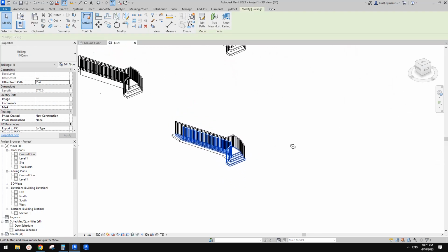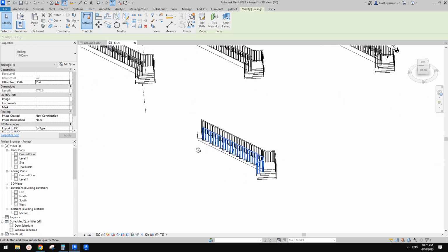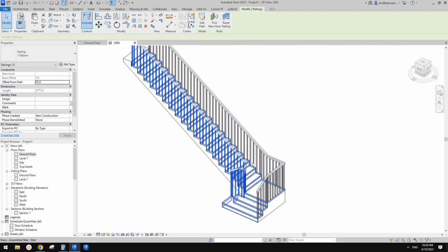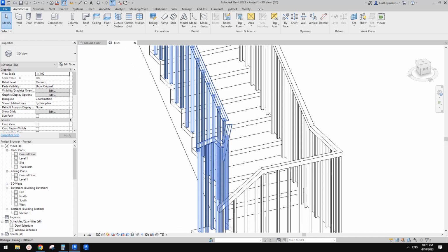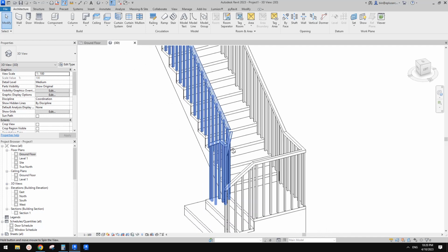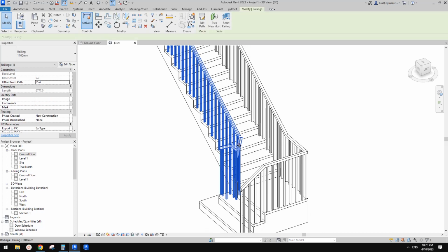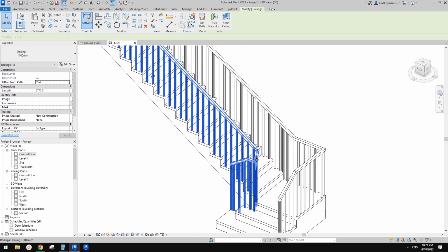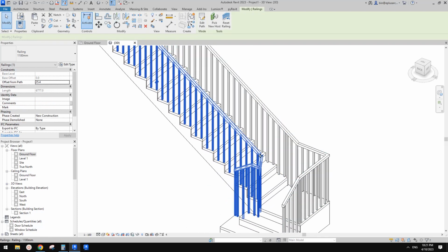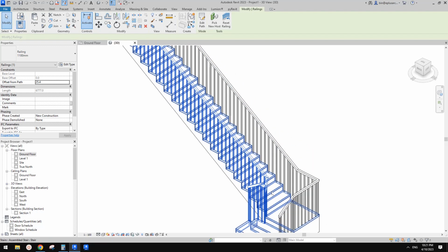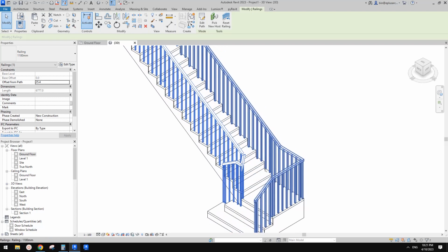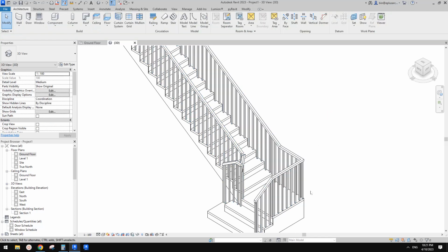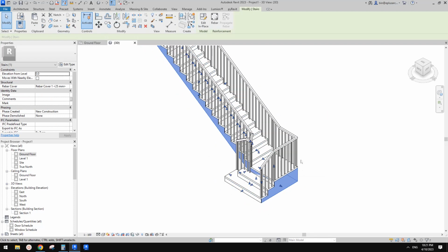Okay, so yeah, stairs is quite tricky, sometimes it's hard. So for example, this, if you ask me, oh, this is broken, can we fix it, I would probably just model in place instead, because it's just not an easy tool to use. So yeah, model in place it's not bad.